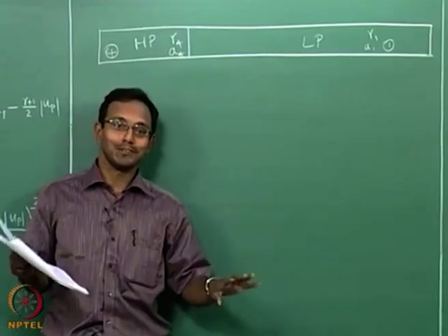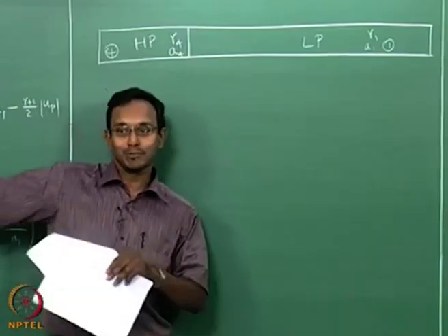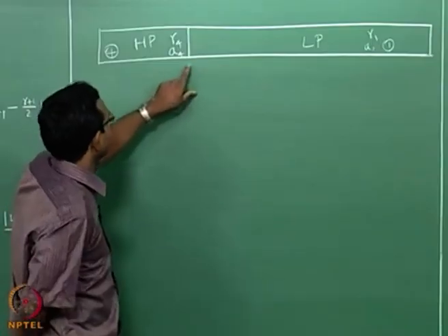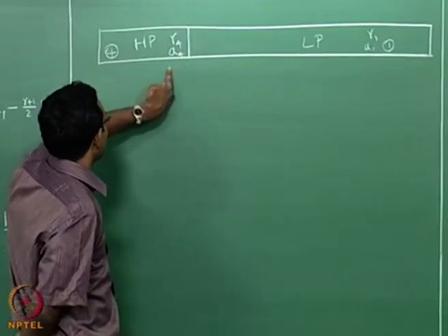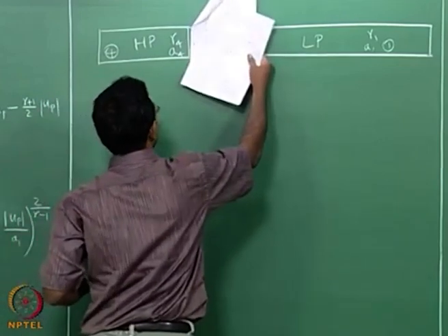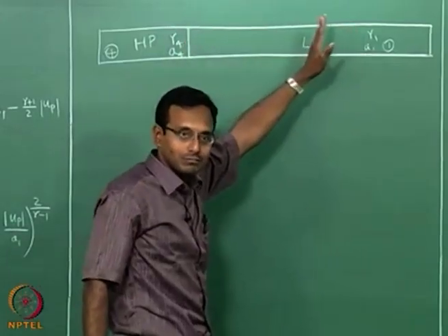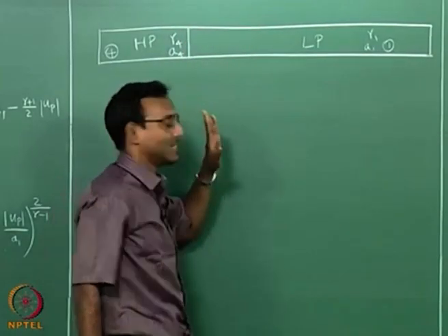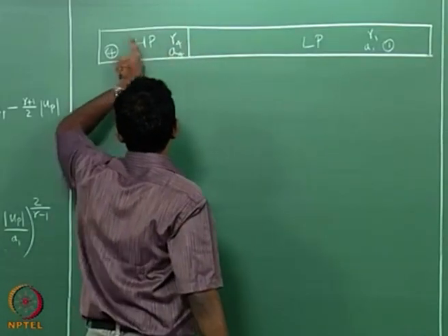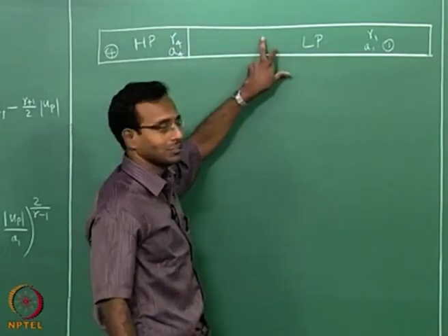We already talked about this problem. And what happens to the outside world if there is some people standing there? They are going to be pushed out more away from the gate. Okay? So what is going to happen in here is there is going to be an expansion wave that will go in this way. If I look at only the high pressure gas section, it looks as if there is a piston that moves out at some speed, I do not know what speed as of now, at some speed such that expansion waves will keep traveling here and making things adjusted to the other section.